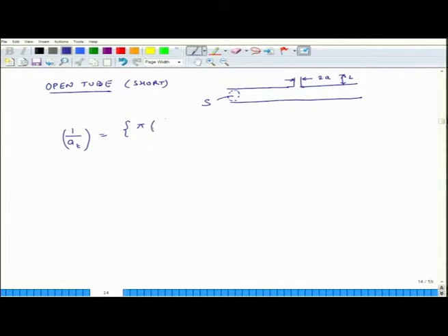So, this equals pi times F L_C, where L_C is the effective length of this tube, and we have now learned how to calculate it, divided by C times (A over L_C) whole square plus R_S divided by 2 pi rho naught C, plus C over F L_C, plus A square over 4 S times C over F L_C, and this entire thing is enclosed in a parenthesis,